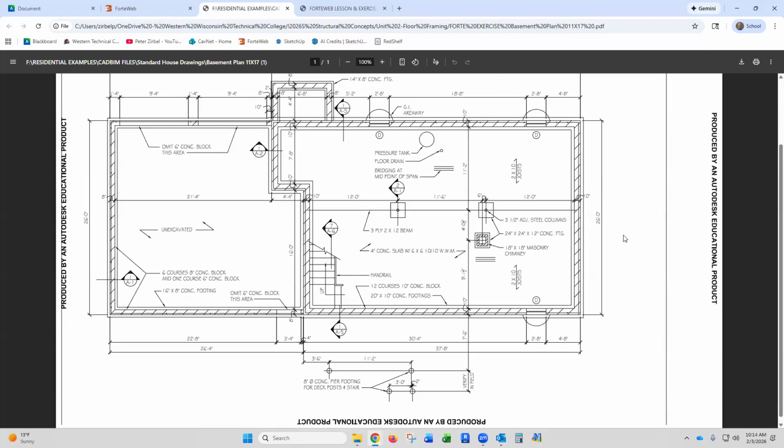So we're going to assume that it's spanning 26 feet out to out and it's sitting on a 2x8 plate. Okay, so the plate is the part it's actually sitting on. It's not sitting on the 10-inch thick concrete wall. It sits on a wood plate. Sometimes they make them out of 2x6, sometimes 2x8. What do you guys typically see on the site?